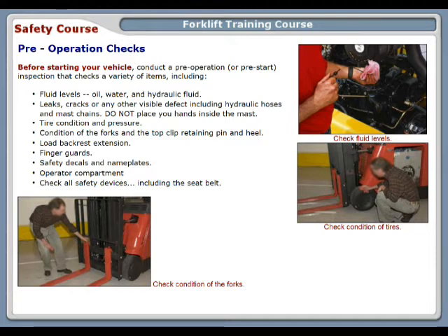Check condition of all forks and the top clip retaining pin and heel. Check the load backrest extension, finger guards, safety decals, and nameplates. Fully check the operator compartment. Safety check all devices, including the seat belt.